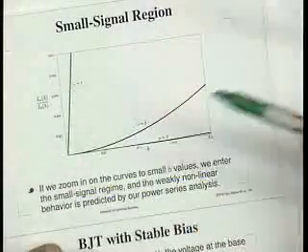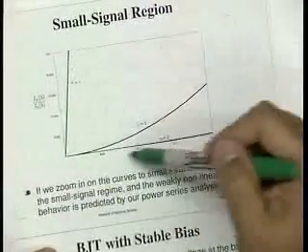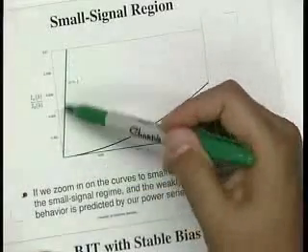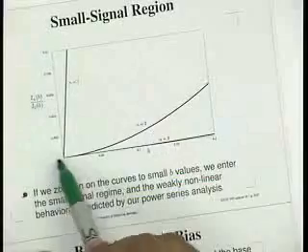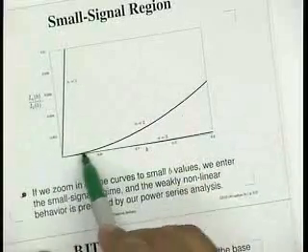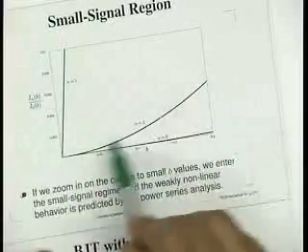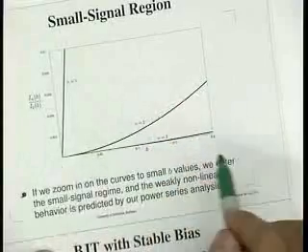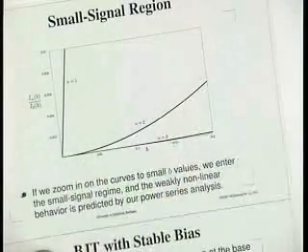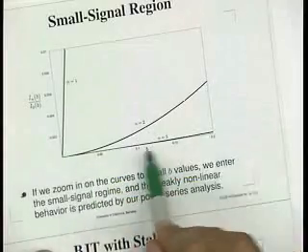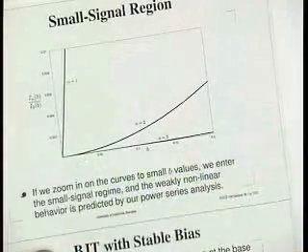It's telling me that as I increase the input power, the output power is increasing in step. And this is how much the second order is increasing, right? For very small signals, this should increase roughly like x squared, or b squared. And so at very small values, I would expect this to be parabolic. And this should be like x cubed or b cubed, and so on and so forth.